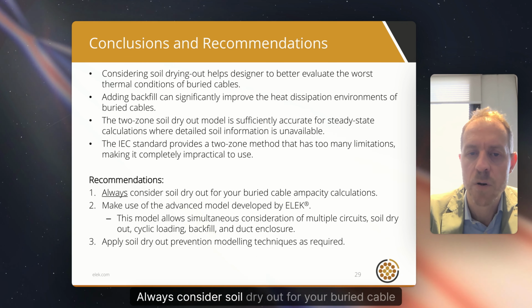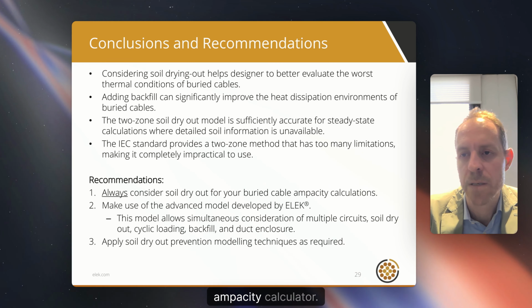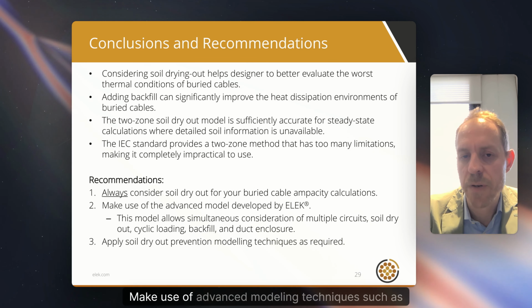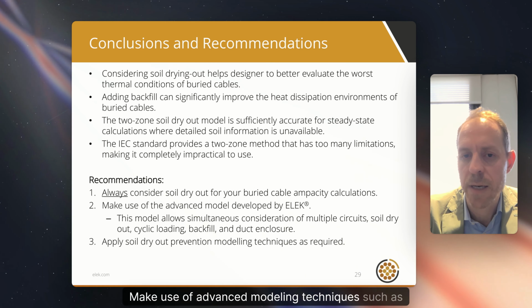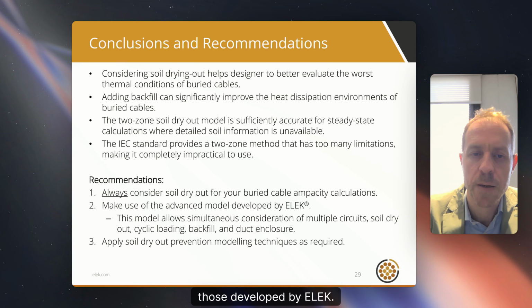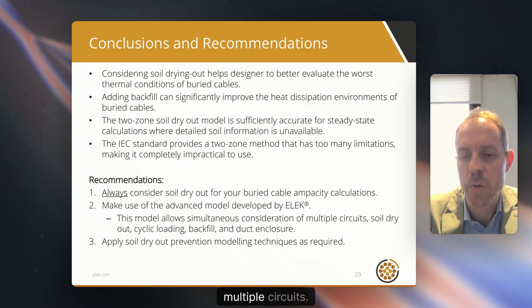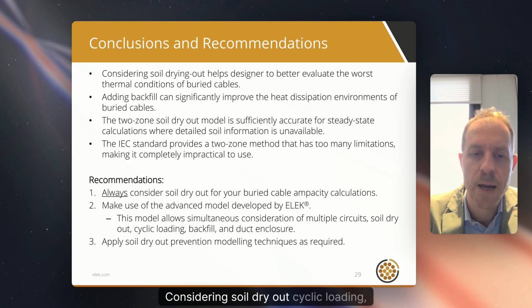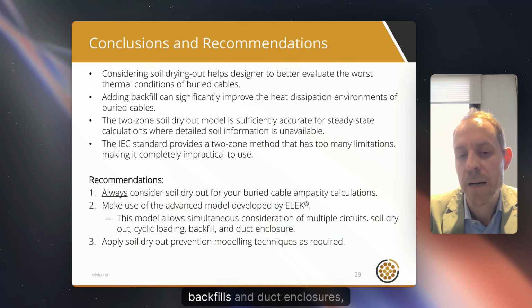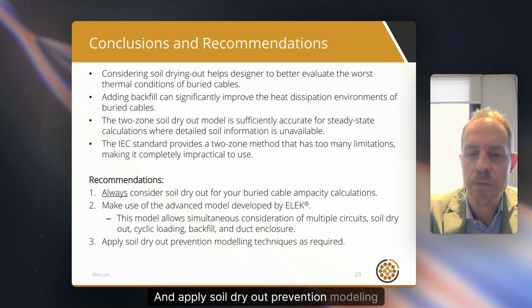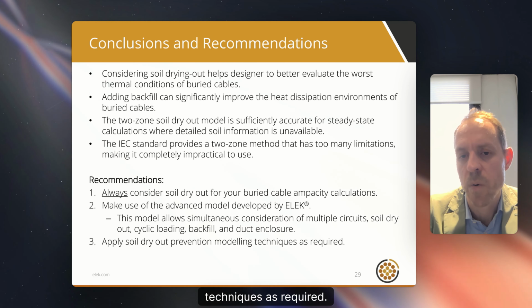Always consider soil dry out for your buried cable ampacity calculations. There's no exceptions really. Make use of advanced modeling techniques such as those developed by ELEK. Our model allows simultaneous consideration of multiple circuits, considering soil dry out, cyclic loading, backfills, and duct enclosures, and applies soil dry out prevention modeling techniques as required.